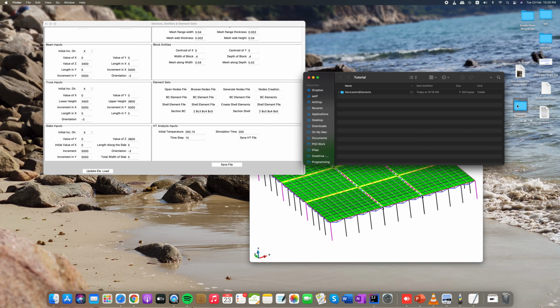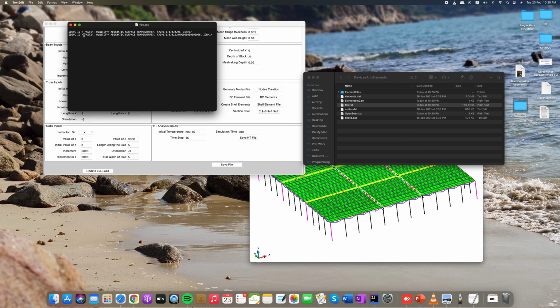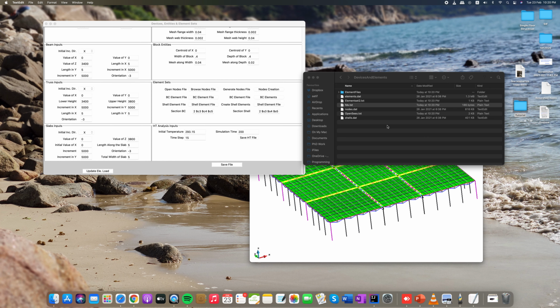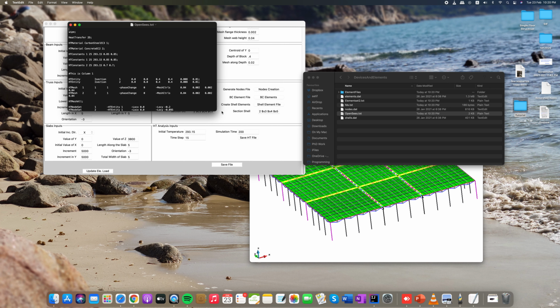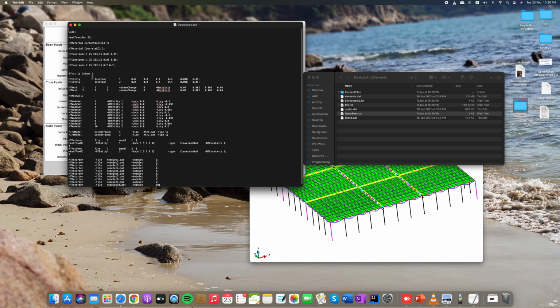If you see there, it was creating FDS devices. The quantity is adiabatic surface temperature, 0.9 to 0.85. Don't worry about it, FDS will run it and you can change it. So IOR +1. This is how your FDS device is created. And similarly, if you go to OpenSees, it creates different I-section entities.